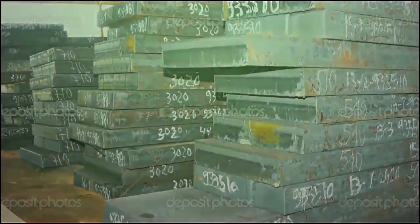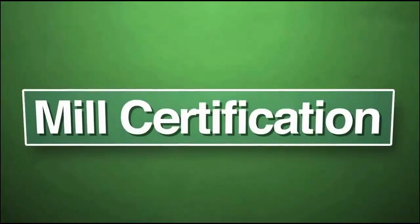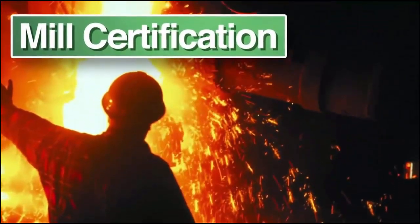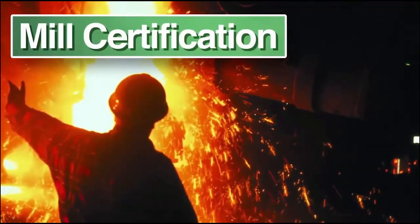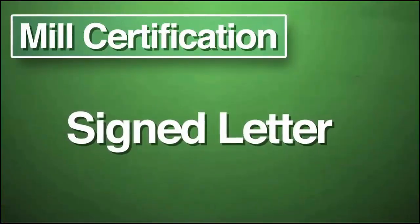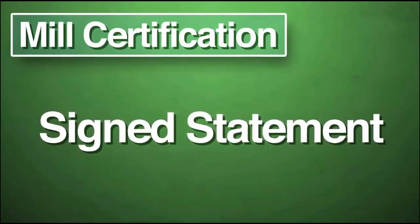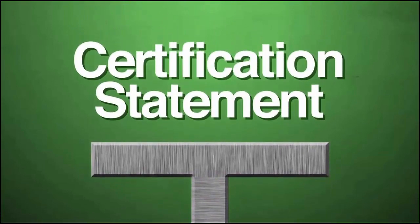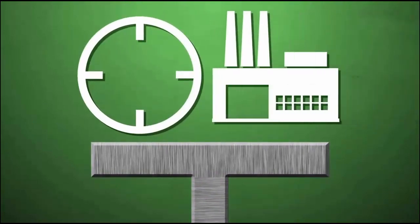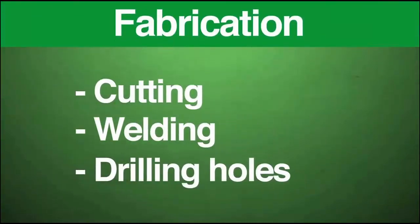One piece of documentation you should expect to receive for all steel and iron is the mill certification. The steel producer prepares the mill certification to prove that the raw steel or iron was smelted and formed in the United States. The certification can be a signed letter or a signed statement included on delivery tickets. Fabricated structural steel shapes must have a certification statement showing the location of the fabrication plant and information about the originating mill work. Fabrication includes cutting, welding, and even drilling holes.